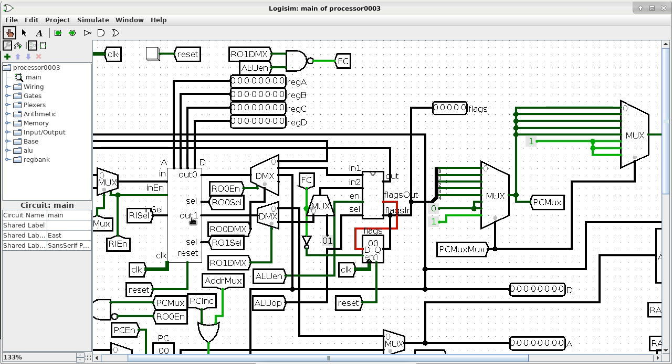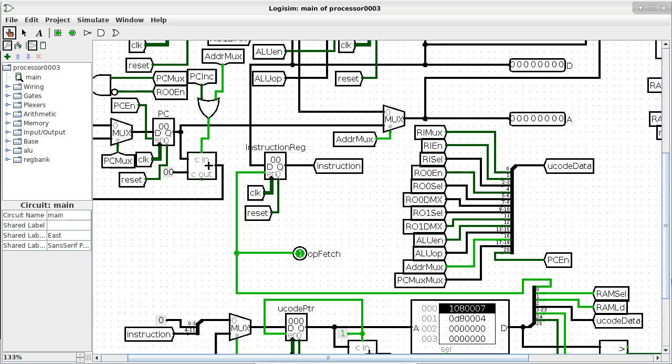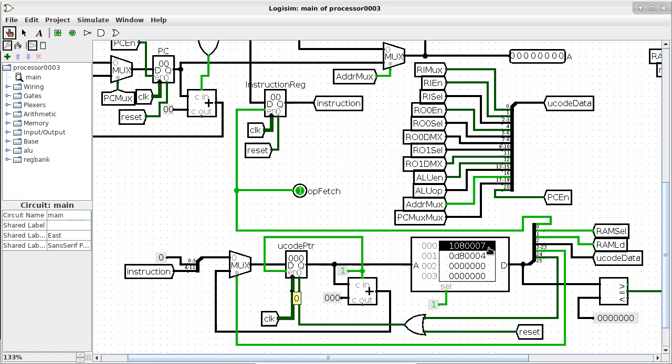Those are the bits in the ROM. So the ROM is basically what it's using to configure all the switches, to configure all the enable pins, to configure whether we are reading from RAM or writing to RAM and stuff like that. So all of these bits that we have stored here, 26 bits for each slice of time, are controlling each individual zero and one so that I can get all the switches done correctly.